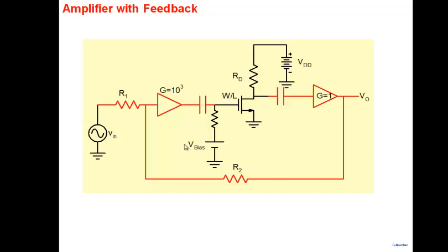So sometimes an amplifier that you see here will be used as a standalone amplifier. But at other times, this common source amplifier will be embedded in a larger amplifier. You can see here, this is my common source amplifier. Before that there is some stage, after that there is some stage. It's a part of a large multi-stage amplifier.